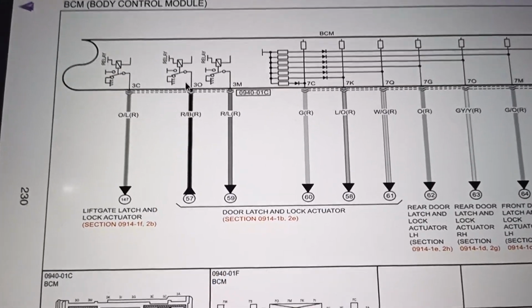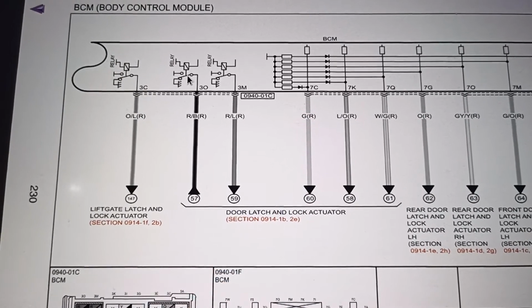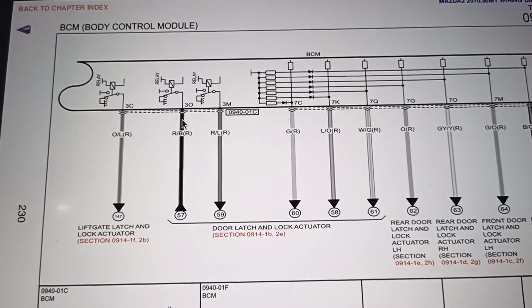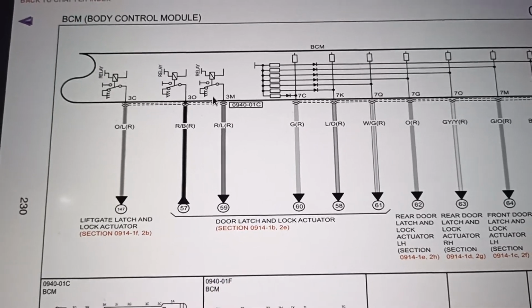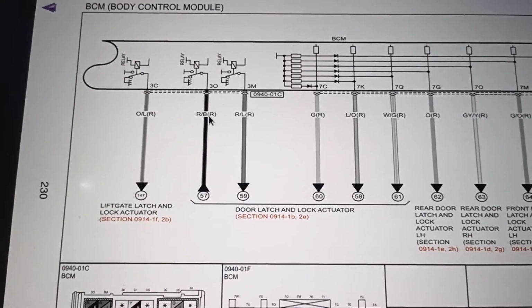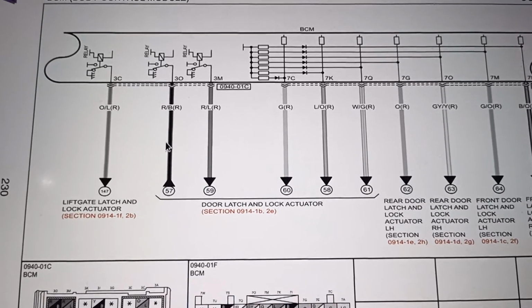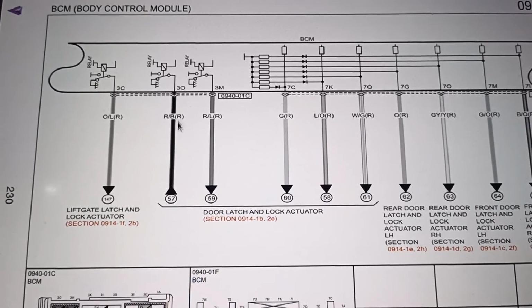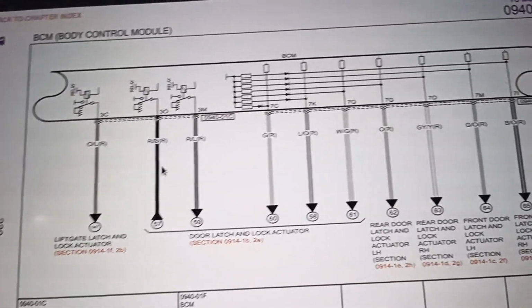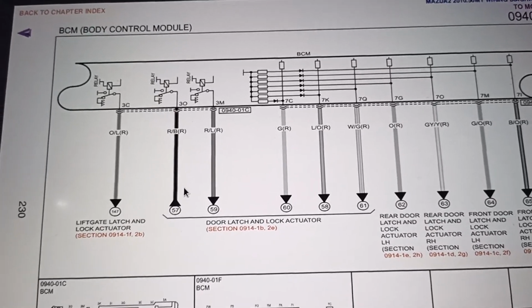Whenever you want to unlock or lock, one of the two corresponding relays switches that ground to 12 volts. So now the motor will have ground from one side and 12 volts from the other side, depending on whether you want to lock it or unlock it. So what you need to do is actually measure which one gets the 12 volts when you're unlocking, because we need the unlock signal, and that's the red with black. This wire gets 12 volts when we're unlocking the door. So we splice into this one and we're ready.